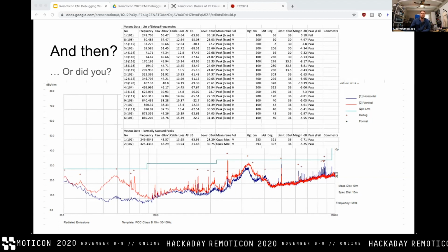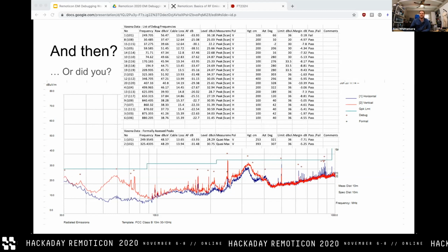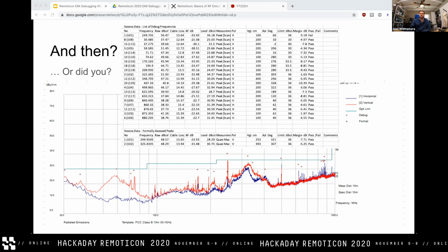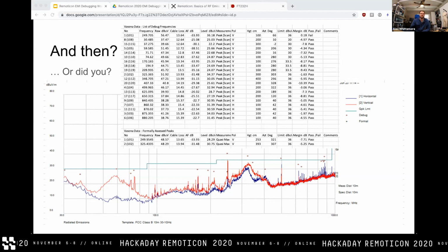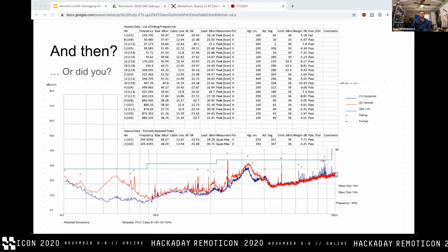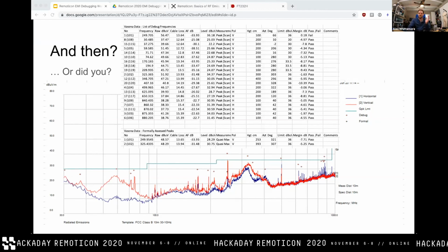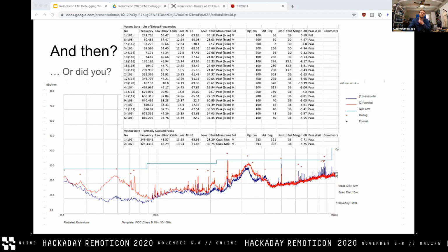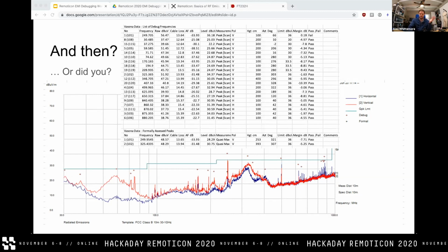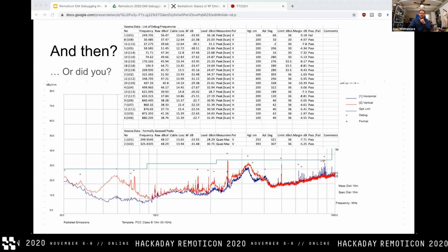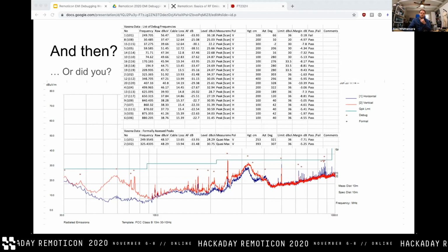So yeah, you have to be very careful about whether your test scheme actually exposes all of the potential failure modes in RF testing, and also make sure that your firmware isn't doing something stupid that it doesn't actually need to do to violate those. Speaking of contrived stupid firmwares, that's what we'll see later on the tiny FPGA, where, okay, this device is super simple. How could it possibly fail emissions testing?